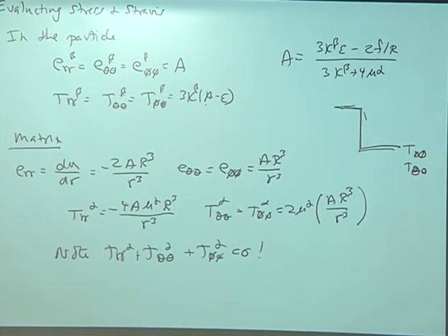Okay, and so now the whole audience here is thinking phase field, right? If this is a phase field model, and you have this jump, you're doing exactly the same thing that you did to the jump in concentrations across the interface in the Cahn-Hilliard model. You're going to replace this with a smoothly varying function as you go across.